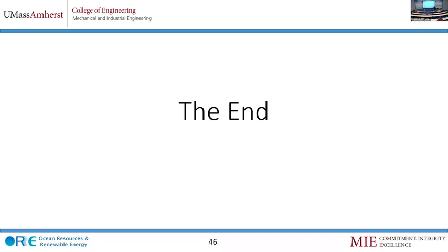Right, but these catenaries are expensive, right? So what if you have more synthetic rope and not this heavy catenary, even if it's more like a linear spring down there? Yeah, definitely. You can go for an all synthetic type system. There are other challenges too, as you know, synthetic line touching the seabed creates all sorts of challenges because of sand getting into the rope and vibration.